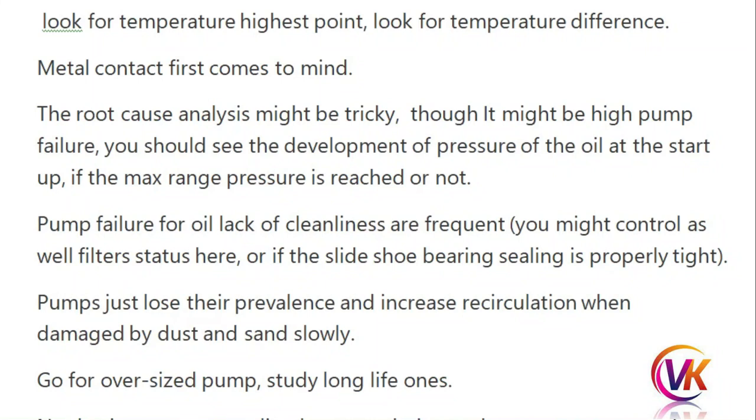You should see the development of oil pressure at the startup, whether the max range pressure is reached or not. Pump failures due to lack of oil cleanliness are frequent. You might also check the filter status, or whether the slide shoe bearing sealing is properly tight. Pumps slowly lose their efficiency and increase recirculation when damaged by dust and sand.